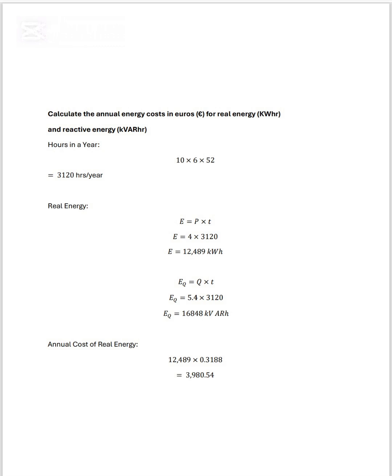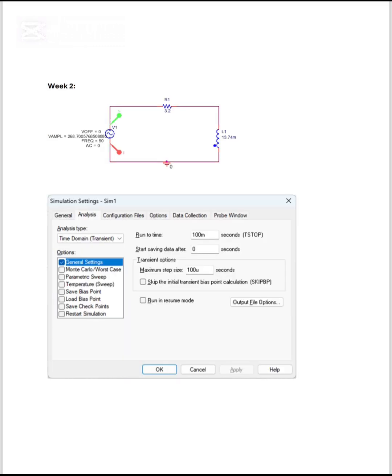It is a dimensionless number between 0 and 1. Real power is the actual power dissipated as heat or used to do work, measured in watts. Apparent power is the product of the RMS voltage and current, measured in volt-amperes. Formula: PF = cos φ, where φ is the phase angle between voltage and current.